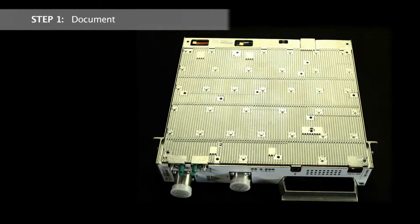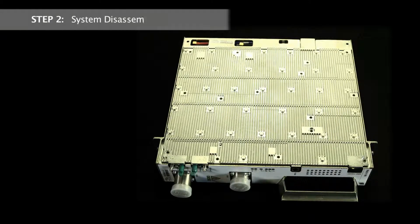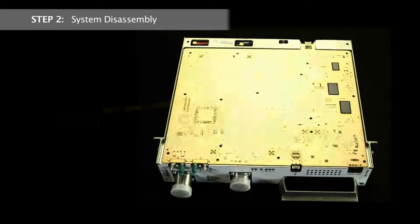The first step is to take the unit and to write down all of the mechanical dimensions for the system. The second step is to then disassemble the unit into its major components. What you see is the complete unit with the RF shielding intact. Once we have removed the RF shielding, you then see the back of the RF transceiver printed circuit board that is completely plated in gold.